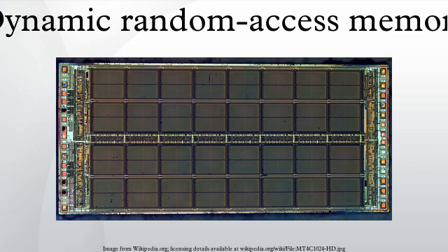The CK and WCKs are phase-aligned during the initialization and training sequence. This alignment allows read and write access with minimum latency. A single 32-bit GDDR5 chip has about 67 signal pins and the rest are power and grounds in the 170 BGA package. Synchronous dynamic RAM.